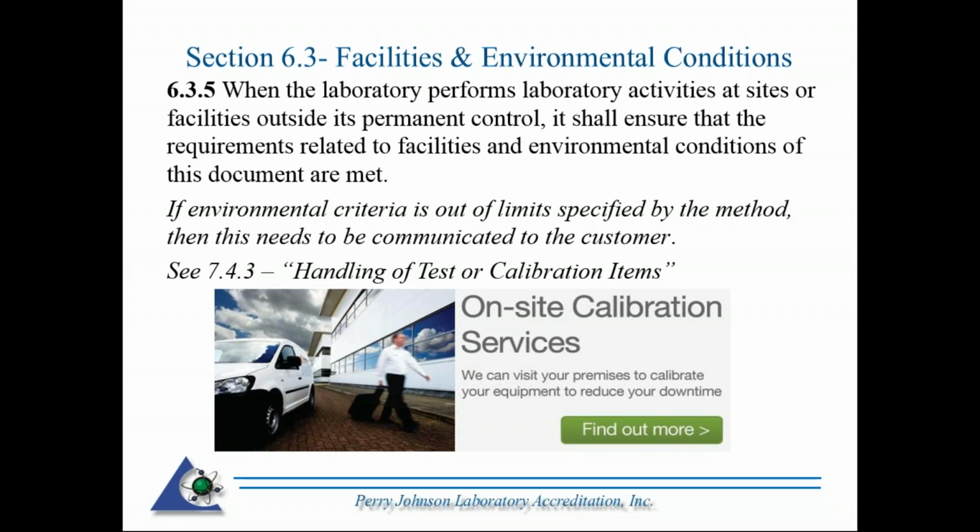Let's say you were to arrive at the customer's location. Temperature was approximately 7 degrees Fahrenheit. Humidity was at 30% RH. Hence, they're well outside of the documented and specified conditions for the calibrations to be undertaken.